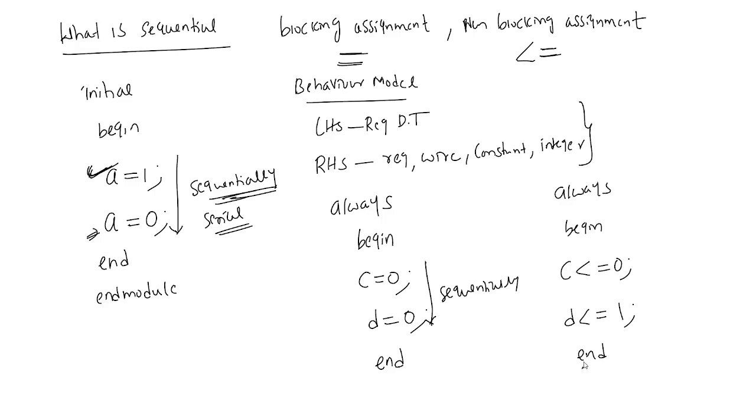If I write like this, this will execute parallel. Non-blocking assignments will execute parallel. Is it fine with respect to blocking and non-blocking assignments? Yes.